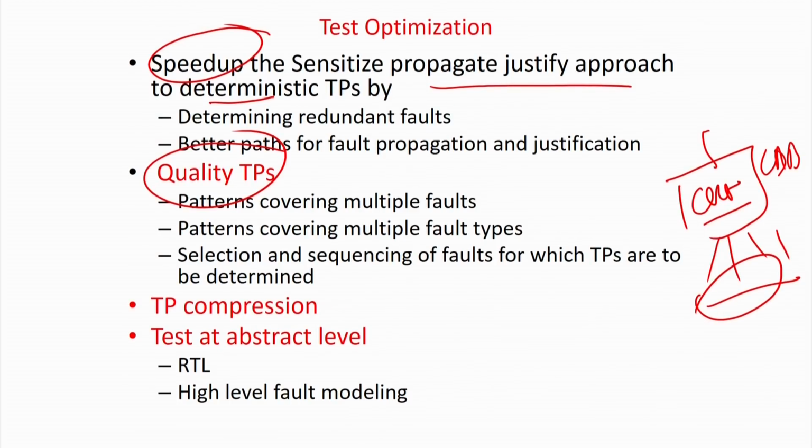Because, as I told you, one fault, one pattern, I am not bothered to take that pattern. But one pattern, 10 faults, I am very happy with it. Because if I apply one pattern, 10 faults will be detected. So I need better quality test patterns.